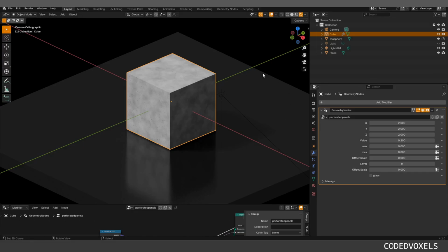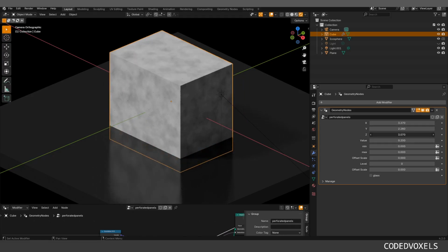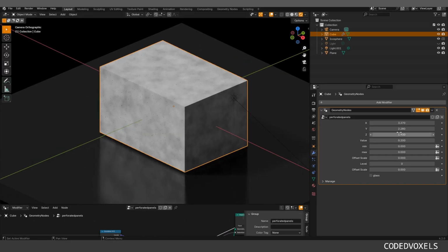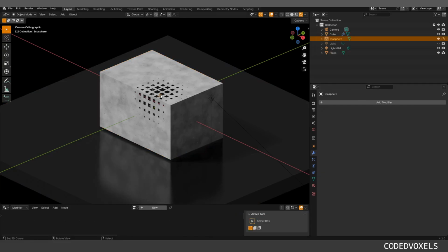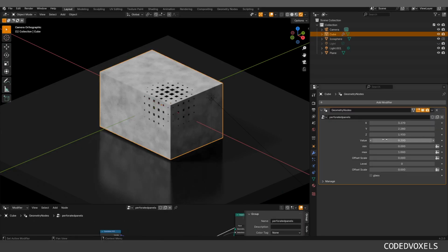And just as an example, I'm going to show you this project right now, which we're going to be developing today. We start with a very simple parametric cube, but the interesting thing is that I wanted to make a perforated panel sketch, snippet, geometry node tree, however you want to call it, noodle soup. So the idea with these parametric perforated panels is that you can control, for example, the size of the panels, then you can move an object around to change how much you perforated them.